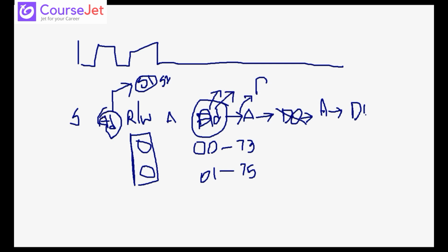To write this address we give the write bit as 0. But at this address location I don't want to write, I want to read. So after giving the second address, give the read operation signal, not directly the acknowledgement. After giving a read signal, whatever comes next is your data to read.